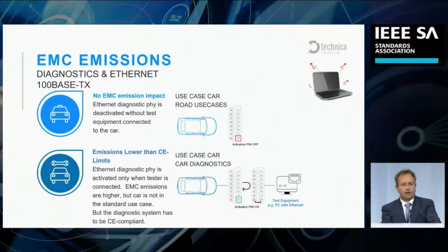If the activation pin on the OBD connector is off, that means there is no diagnostic system connected to the system, and the gateway detects it and switches off the Ethernet line. So there is no EMC impact on any of the system because the diagnostic PHY is switched off. In the other situation, where the activation pin is on, there is an EMC effect on the cable between the gateway to the diagnostic